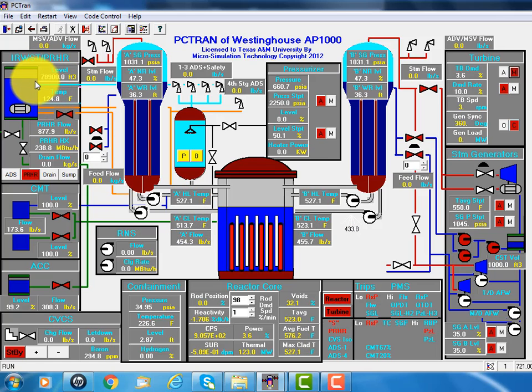So there's no high pressure safety injection pump. And when the pressure is down, when the pressurizer level is going down, the coolant makeup tank will open. And they are physically also located higher than the core. So once this valve automatically opens, the coolant will make up the loss. And the third layer of ECCS is the conventional accumulator.